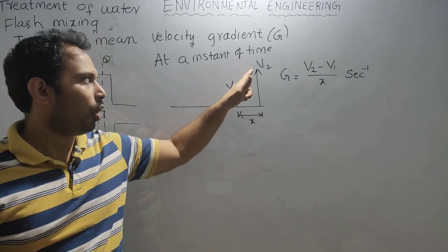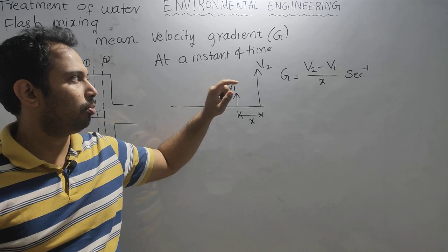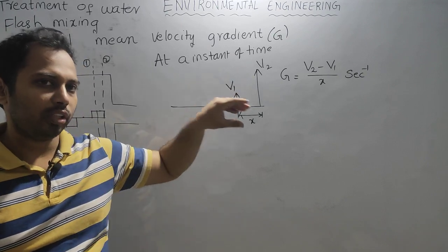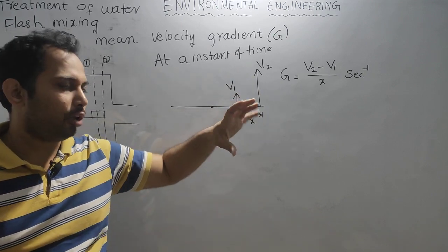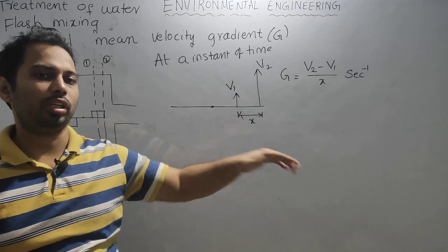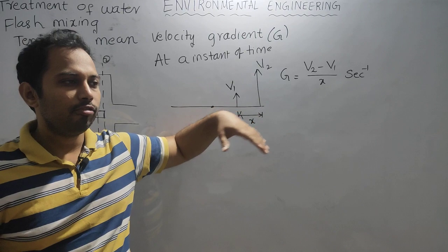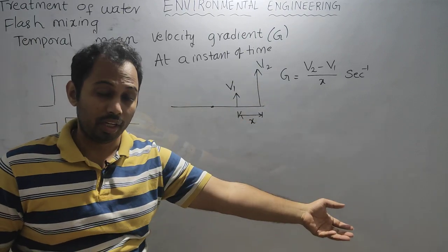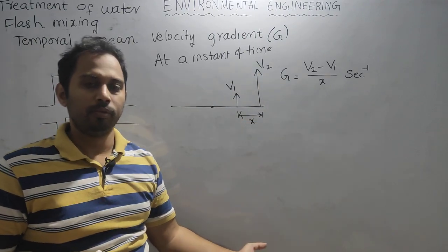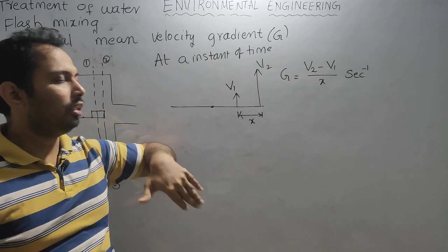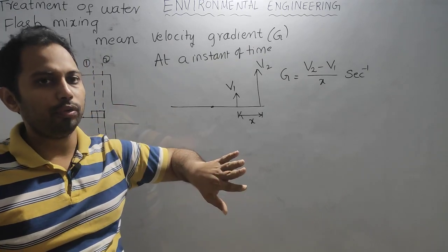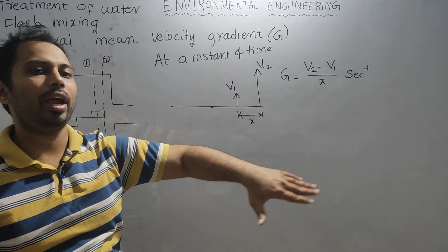You are looking from the input point of view. When you give power, the shaft will rotate. If the shaft rotates, it will induce velocity in the water. So calculating G from the velocity of the water is from the output point of view. Similarly, you can find G from the input point of view, that means the power supplied to the shaft.